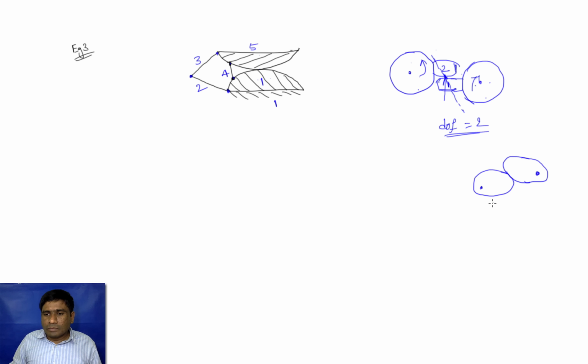So when I am rotating this cam 1 in the anti-clockwise direction, this will rotate the cam 2 in the clockwise rotation, and at this point where it touches, cam 1 is sliding along the surface of the cam 2. So cam 1 is rotating the cam 2 as well as sliding on it. So there are two motions between these cams. So here also the degree of freedom is equal to 2.